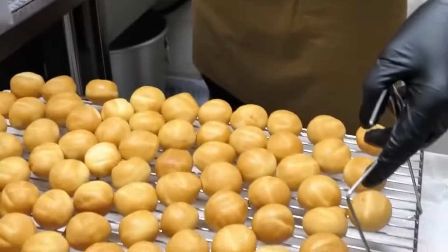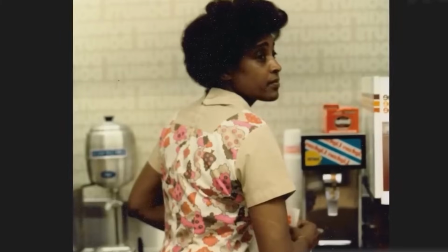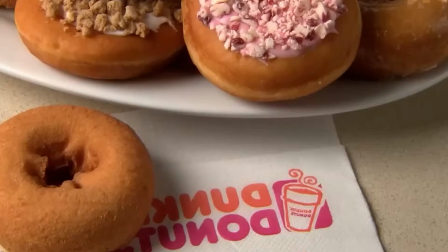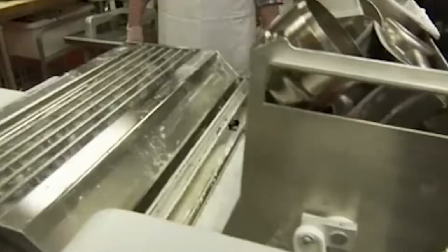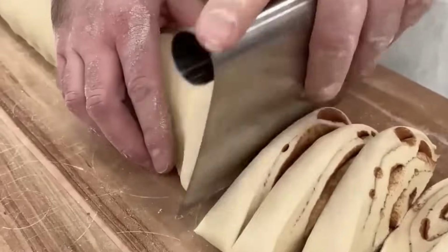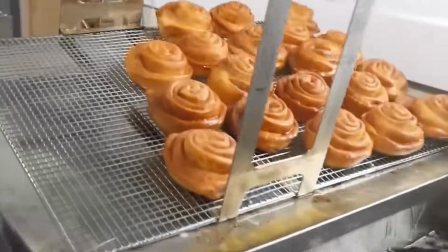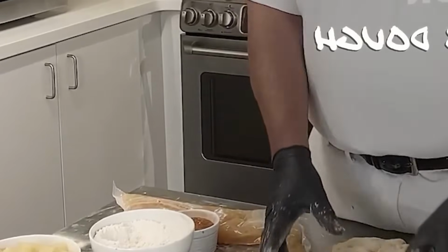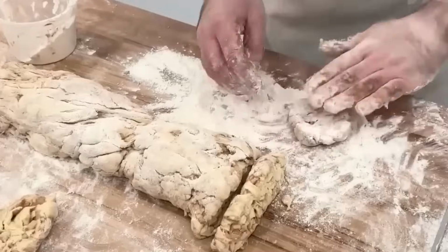Case flaps are glued and sealed using hot melt adhesive heads. Filled master cases are conveyed to a robotic palletizer. A vision-guided robot stacks cases in alternating patterns for load stability. Slip sheets are added at programmed intervals to separate layers. The stack height is optimized for transport requirements.